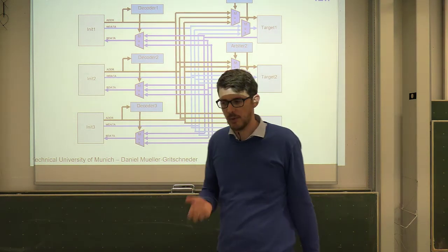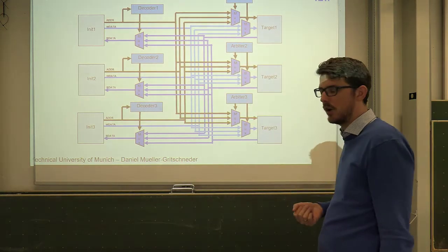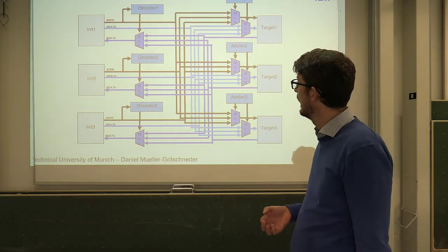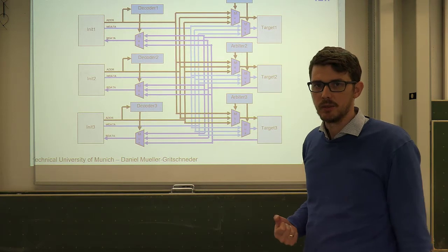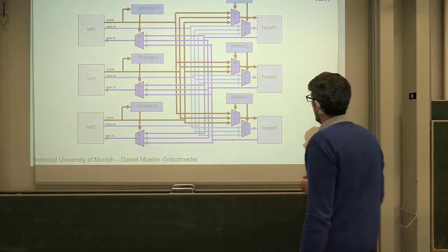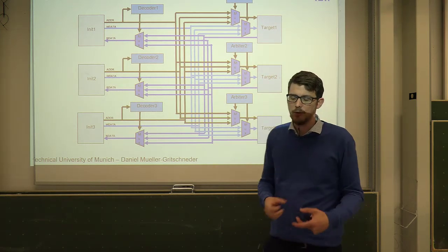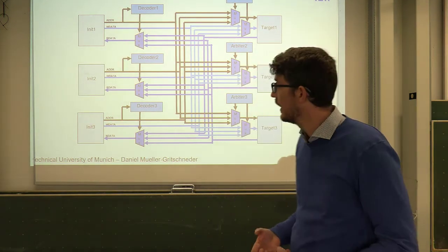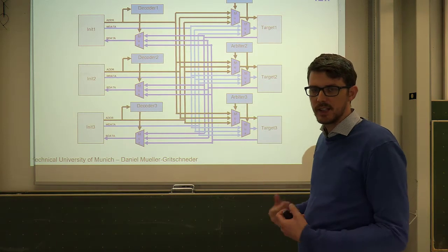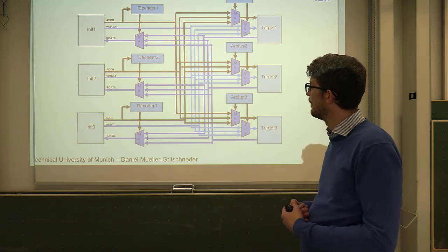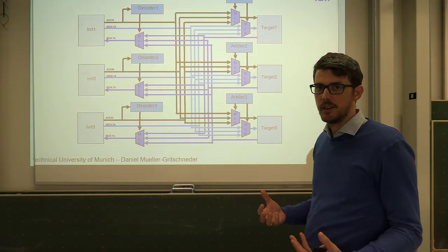Okay, now this of course is very nice, right? So why don't we always do crossbars, right? The issue is sometimes you don't need it. Sometimes if you have a lot of targets, you don't need to have all these parallel accesses going on, because often some of the targets are anyway lazy. So a shared thing would be better.